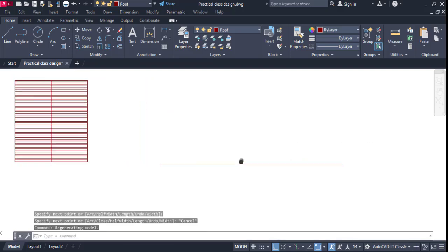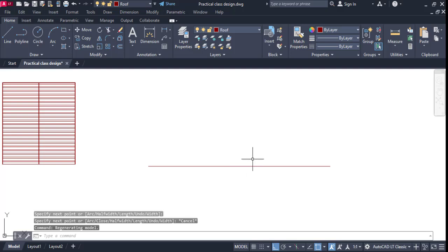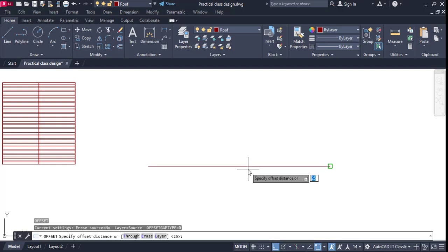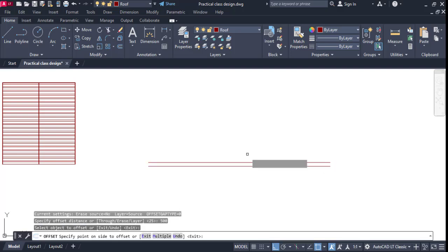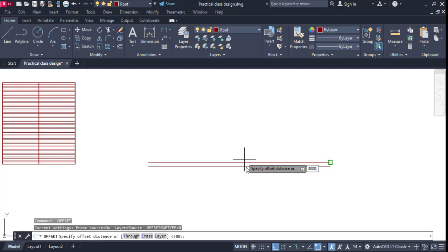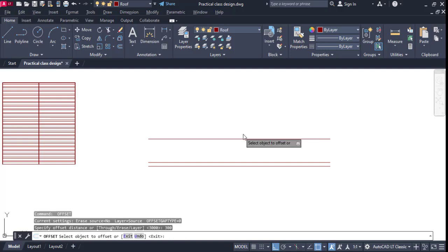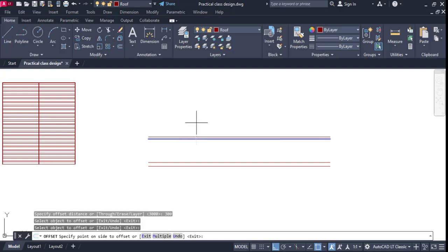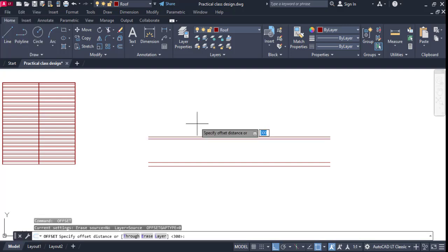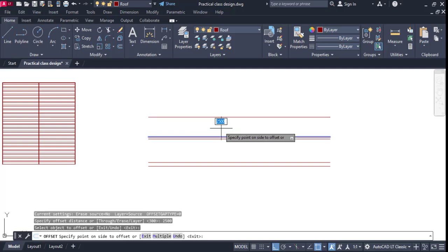From the base of my building, I'm going to take like 500 millimeters to elevate the building a bit. So I'm going to say offset 500 millimeters. Okay, offset again 3,000 as the building height. Offset again. My fascia is like 300 or 400, whatever I want to use, that depends on me anyway. So 300. The next thing is my roofing height, which is going to be 2,500. So coming here and say again, this is it.